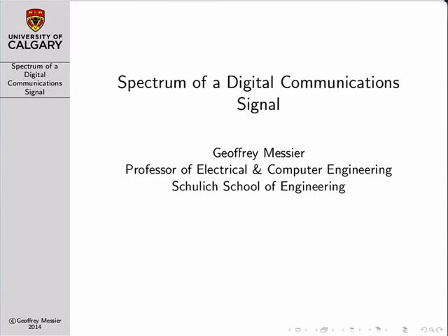And we're going to be focusing specifically on a baseband signal. But as we've seen in our signal representation module, passband signals can be represented in baseband as well. And so that means the derivation that we'll be doing here can be used to represent passband signal spectrum. All you have to do is just take that baseband signal spectrum and shift it up so it's at plus or minus the carrier frequency.